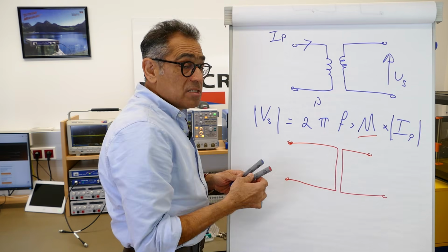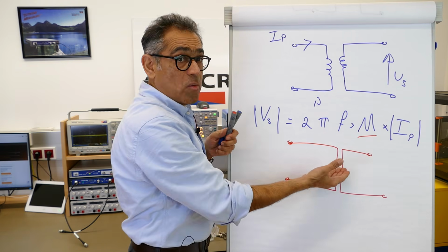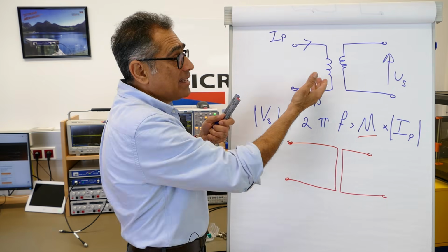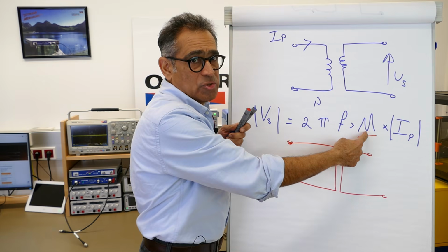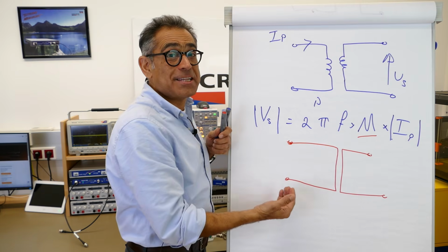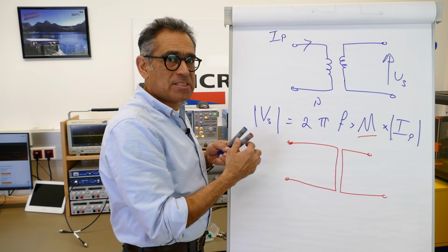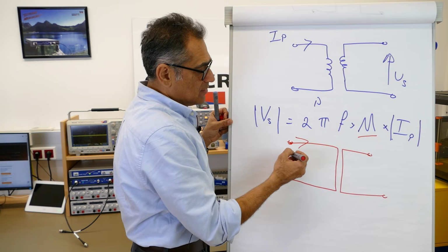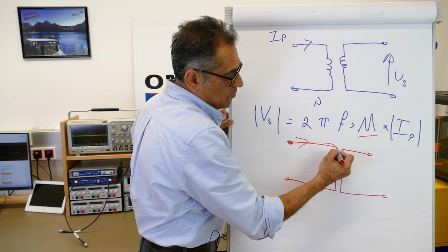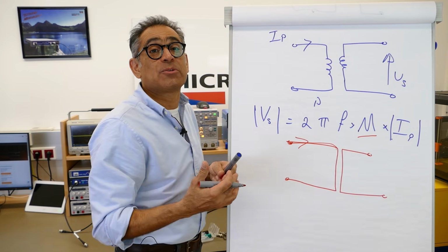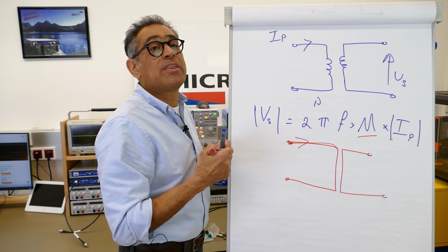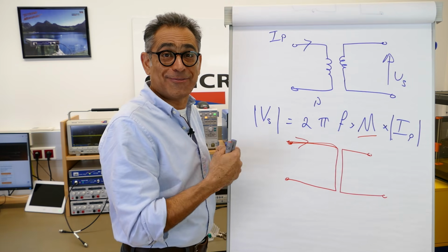The mutual inductance is tiny, it's very, very low because there is no real winding, there's no magnetic core. However, there is some mutual inductance, and if the frequency gets high enough, there will be some coupling. And if you pass a high frequency current from this side, you will see a voltage on the other side. And of course, this is the noise that we don't want, and it's being coupled with a method of coupling that we call inductive coupling.